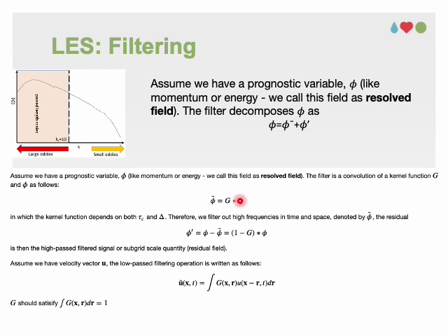Using the defined cutoff wavelength, the convolution is expressed by this integral that represents the area under the curve of the product of 2 functions, as one of the functions is shifted by the variable r.